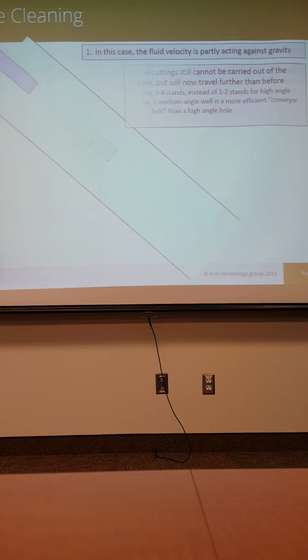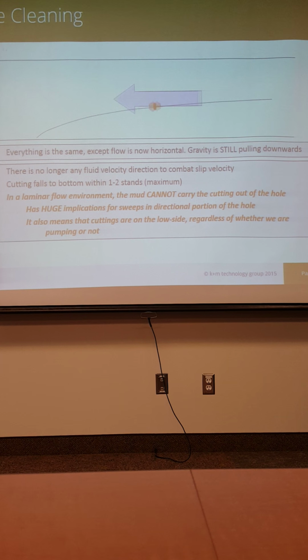Because in a horizontal well, the cuttings aren't going anywhere. When you turn the pumps off, that's where they stay. Whether the pumps have been off for 5 seconds, 5 minutes, or 5 days, the cuttings are no more of a hazard to you. You will not get stuck because of the cuttings in a horizontal well, just by sitting there with the drill pipe. The reason why you get stuck in a horizontal well is because you try to pull the BHA out of a hole that isn't clean.